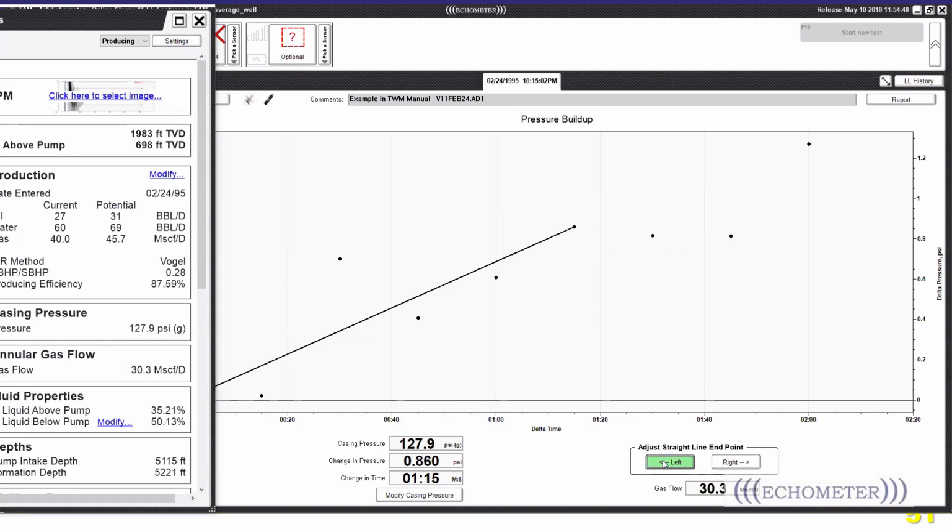And let's say this guy was in a hurry and only let the well run for 15 seconds and stopped the test and said, well, I have a lot of liquid in the tubing and my gas-free pump submergence is 1750 feet, so I have a lot of pump submergence. But if they could wait just 15 more seconds, stopping the test right here, that liquid percentage will drop dramatically, and then we lost 1,000 feet of pump submergence just by that.